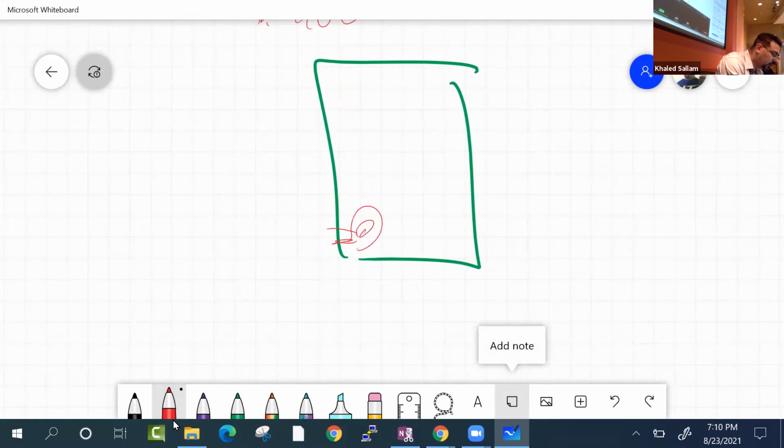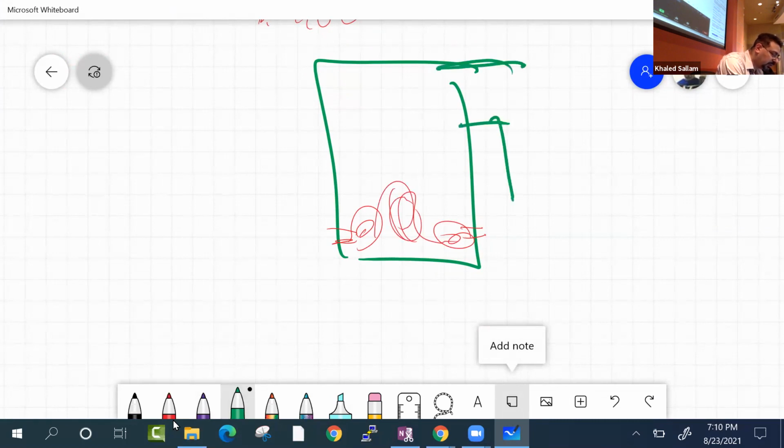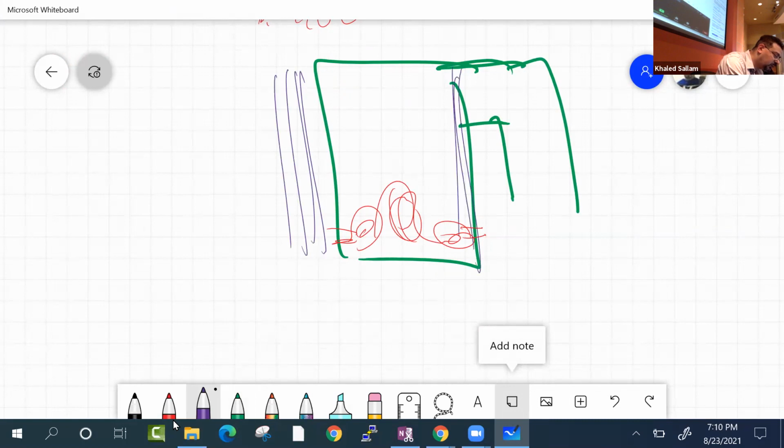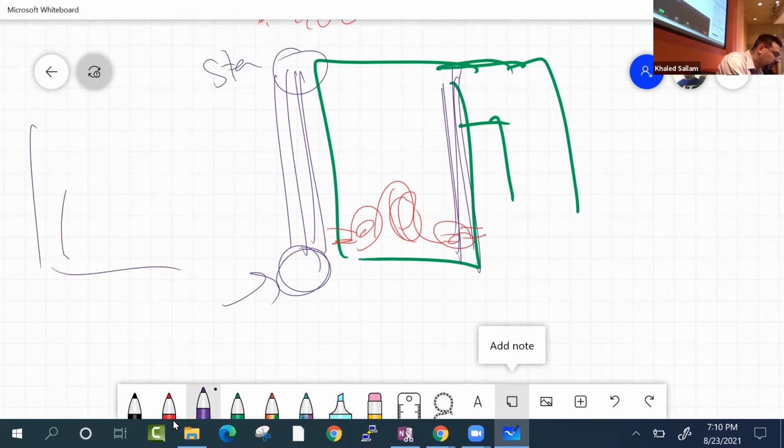Usually the fire will come from the wall like this, and the middle here would be the fire. All of the wall is covered with pipes, and those pipes take the water that's coming in and turn it into steam. So this is the part where you go from HF to HG.